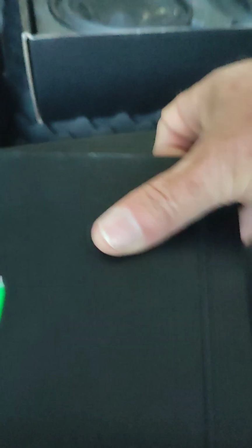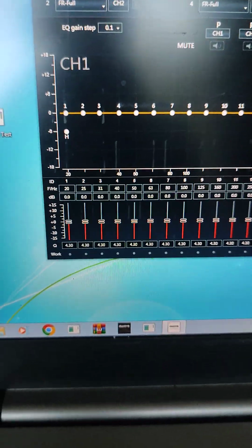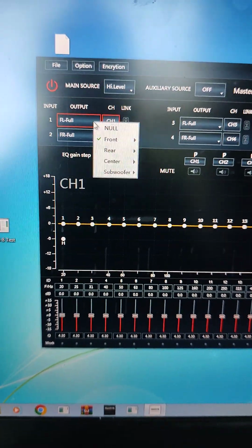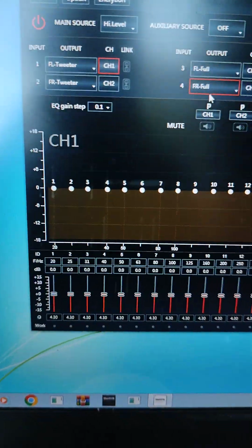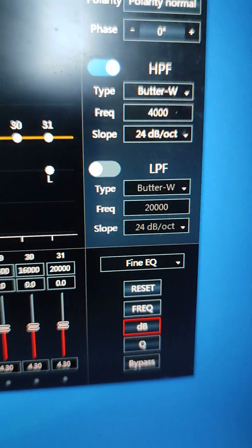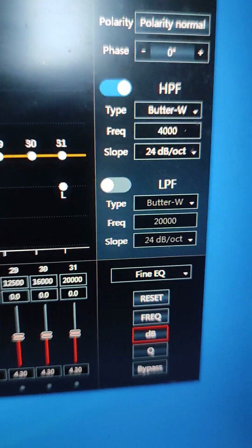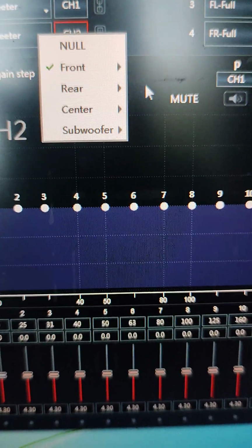Okay, welcome to this. There isn't actually any software that's this advanced at the moment. There's many people been referring to it, but this really gives us superb coverage. Okay, so how should we start? We start by naming the speakers, and you'll see the reason why we do this. If you choose the first speaker to be front, and you choose left, and you designate a tweeter, what you get from the processor is a really helpful guide of what a tweeter should be, and it even gives you a recommended 4000 high pass. And actually, if you just do the default and basically do all of them like that, the processor will make sure that when you turn on, you don't harm any of your speakers.